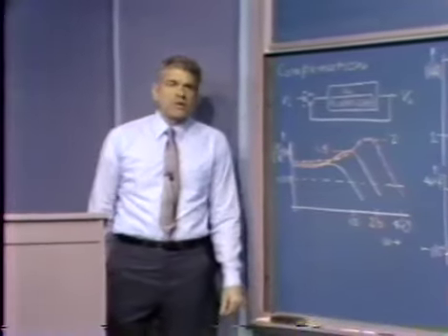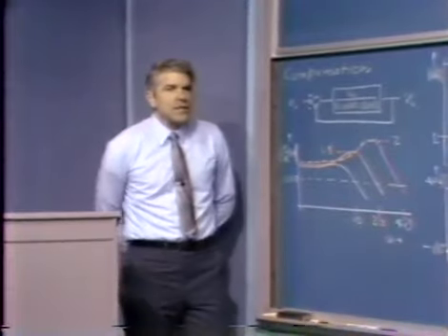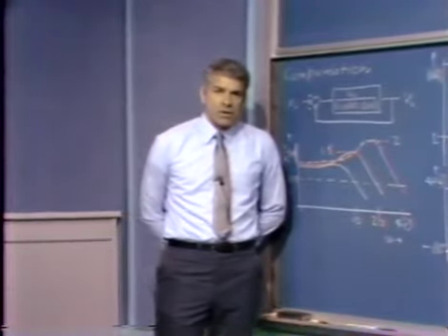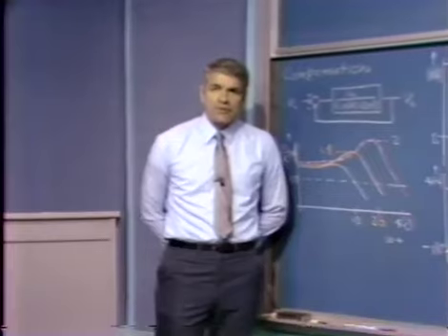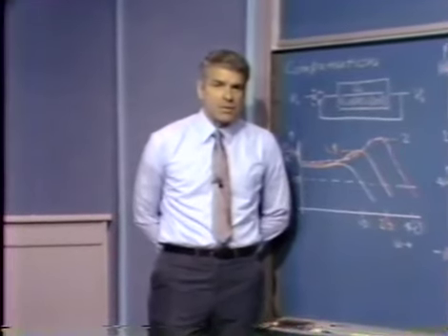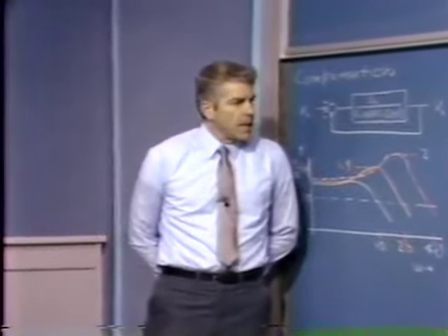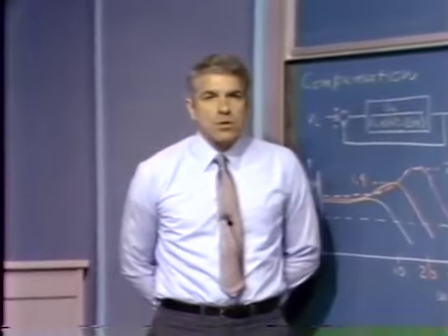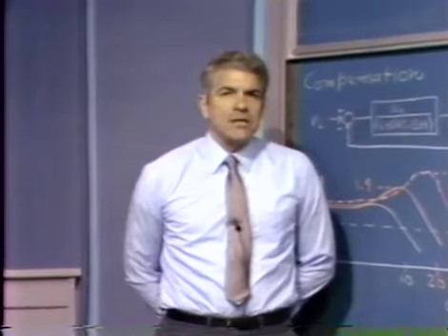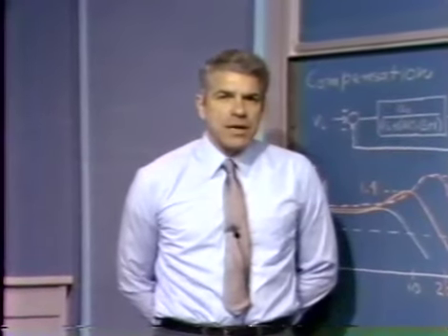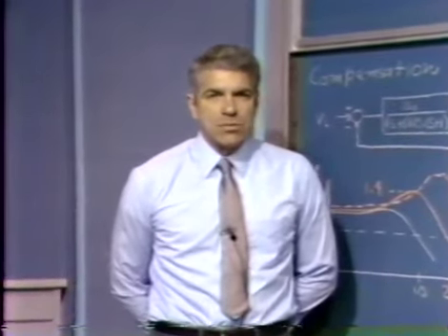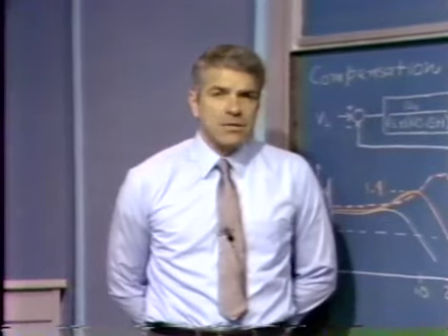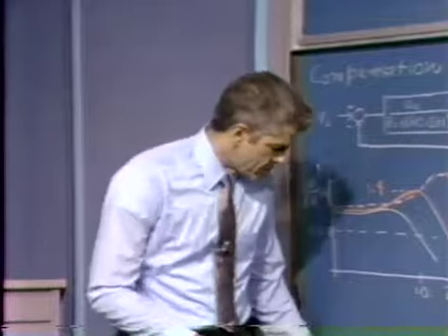Well, that sort of a construction is fairly easily done, although in reality we normally don't even have to do that much work in order to get a good indication of relative stability via frequency domain techniques. And in particular, it happens that the closed loop response of the system is very nicely characterized by several parameters relating to the loop transmission, or the AF product. And I'd like to define those and then see how we use them.